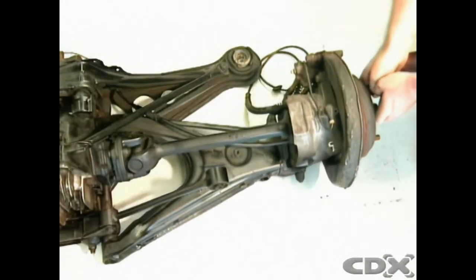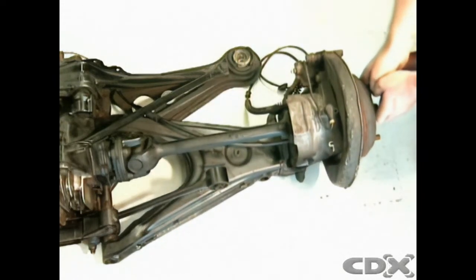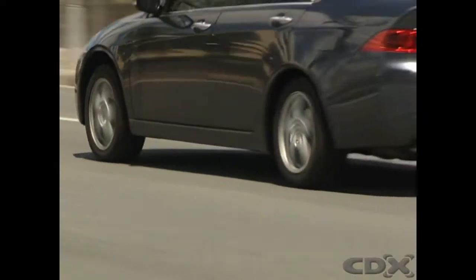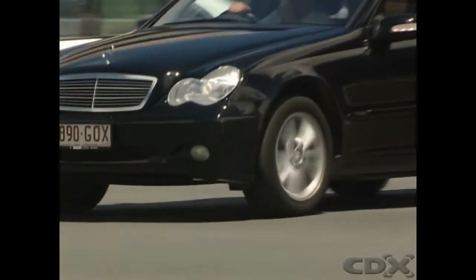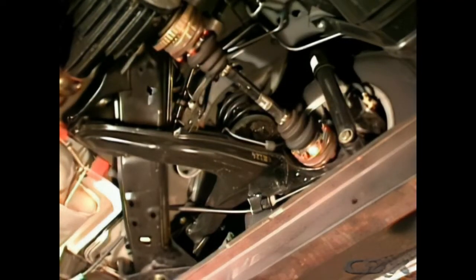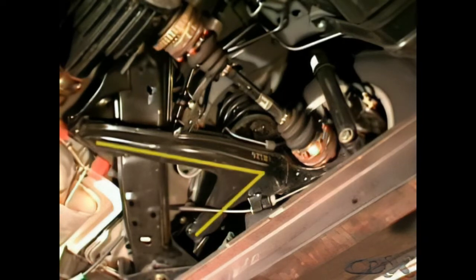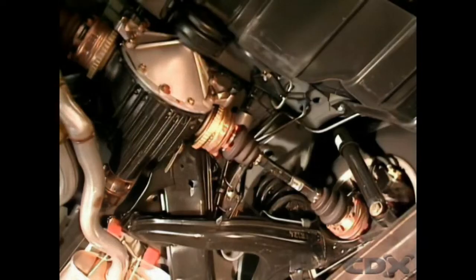As with the front suspension, the lower link has widely spaced pivots to provide stability, and the unequal length links maintain the track nearly constant, although with deflection, some camber change does occur. In some designs, the wheel units are located at the outer ends of semi-trailing arms. The arms are attached to their cross-member pivot points by rubber bushes, and constant velocity joints are used at each end of the external drive shafts.